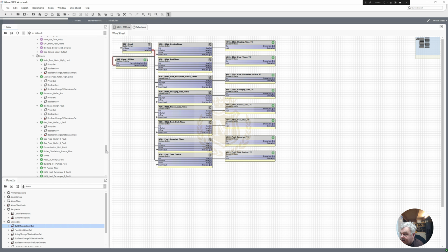It's the only way that I know of doing it via BACnet, because you're going from an IQ3 BACnetting to a Tridium Niagara, Niagara networking from the Tridium Niagara to the cloud, and they want to control the time clocks on the cloud.